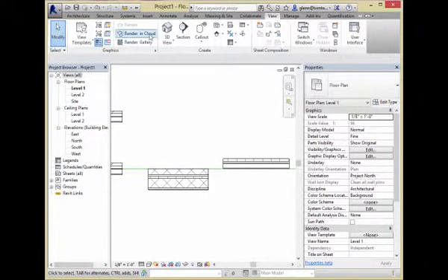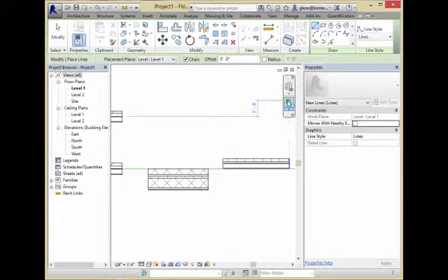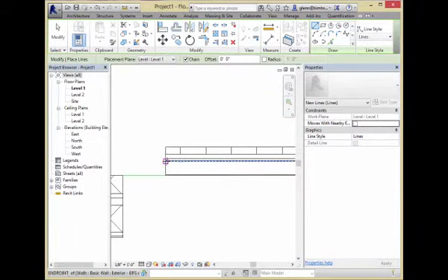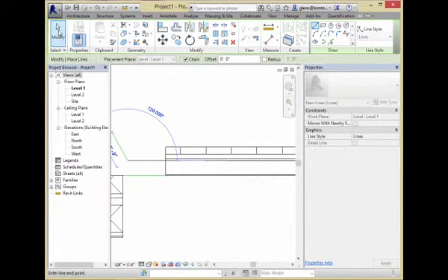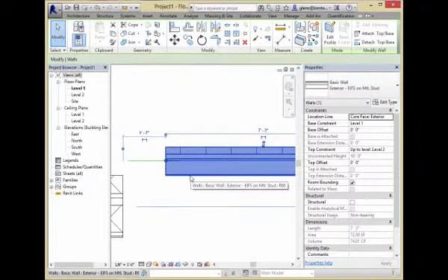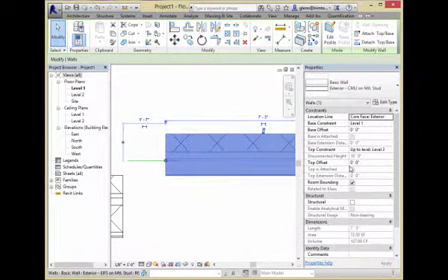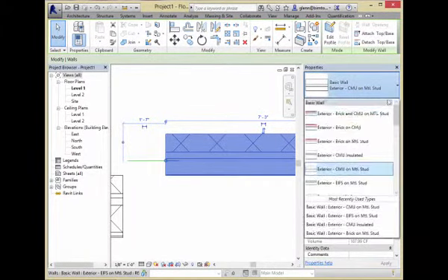What I just did there was I said, okay, I'm going to draw another line just to let you know where it is. I'm betting that it's right there, and we'll show you how to determine that in just a second. What I would like to have happen is, as opposed to everything pivoting around that old line, I'd like it to pivot around this or expand around this. Since that's now the location line on the core face, if I go through and change things, that's going to be the constant point.